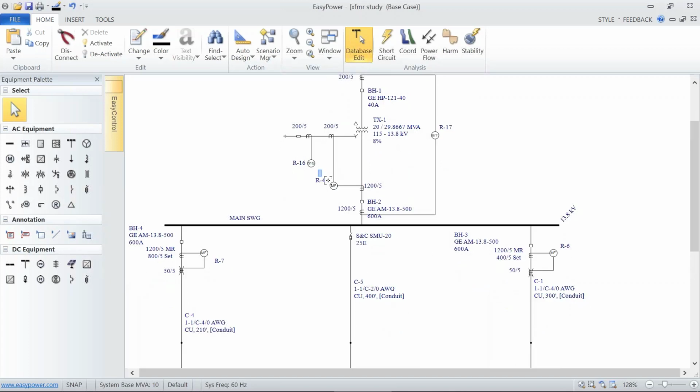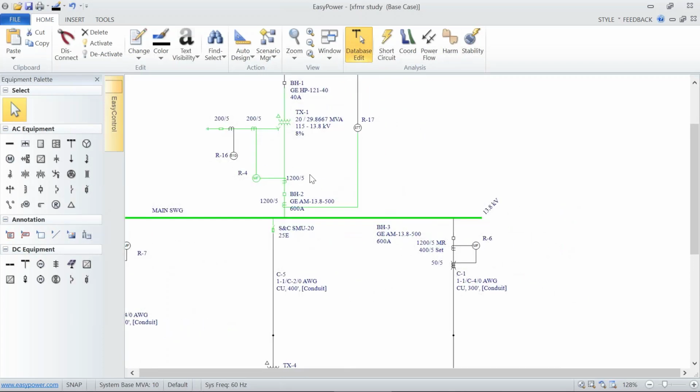In this case, we're looking at protecting the switchgear and the cabling down to the next level of protection. And at the same time, we want to establish or make available the full amount of buffering that the transformer allows on the secondary side.